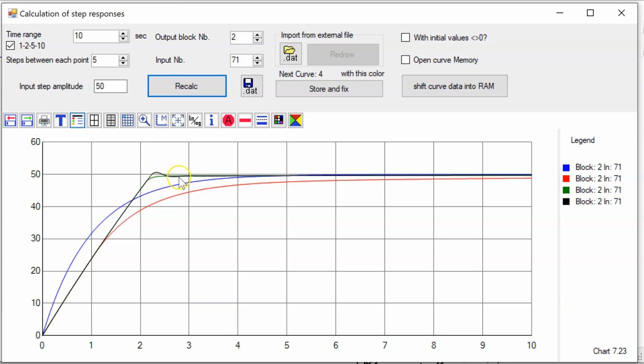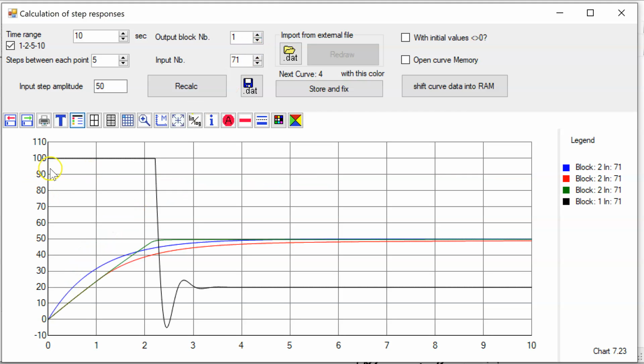Yeah, the speed signal looks fine, but if I switch now to the power signal in this situation, then you see the power signal ends up in a very strong decrease to 0, and here you see furthermore you have negative power, which means the motor want to have negative power, means the car should brake. Yeah, so you get oscillations, and this can of course could be a high mechanical load for all mechanical parts